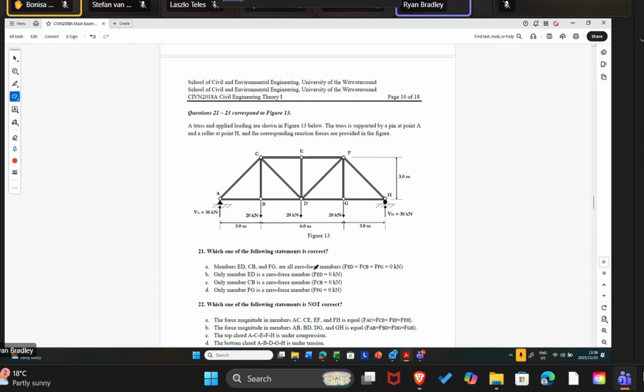What we know is this truss under these forces wants to deflect like this. It means that the bottom chord here is a tension chord. This top chord here is a compression chord. We know this from beams. When a beam deflects under load, the cracking starts at the bottom. That is tension. Crushing occurs at the top, compression. Compression, tension in a beam; compression, tension in a truss. A truss is essentially a beam. These members here are carrying shear forces. The same principle applies. This question is really just assessing our understanding of how forces flow in a truss.